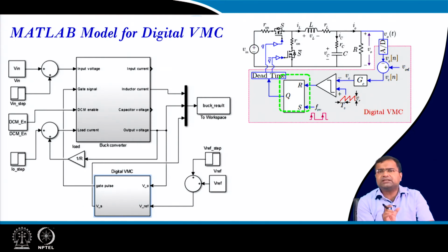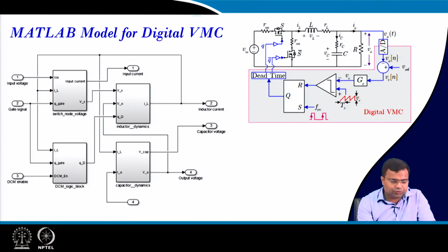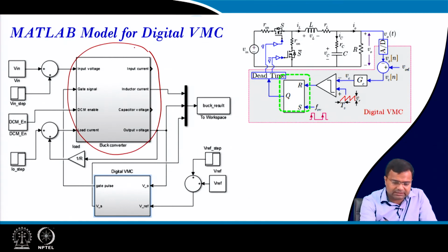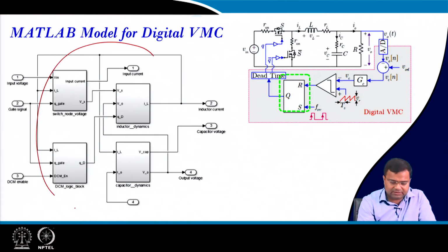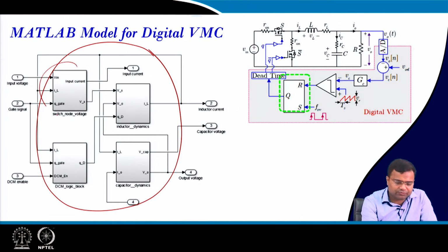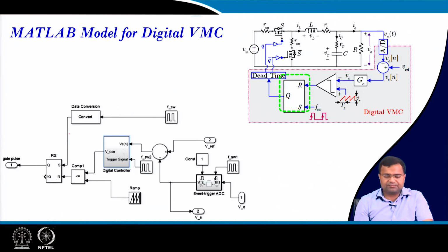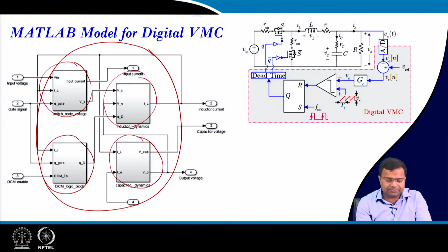So, this is the overall digital voltage mode controller model that we have discussed. If you zoom into this portion, this is the power stage, where we have the switch node voltage, inductor dynamics, capacitor dynamics, and the DCM enable logic. Now, if you go inside the controller,